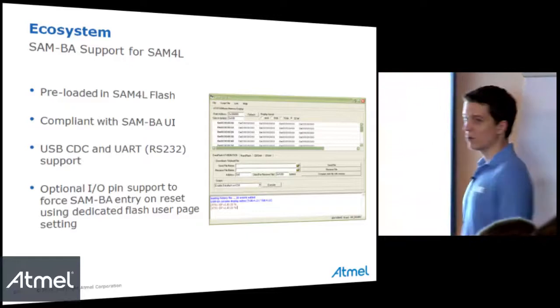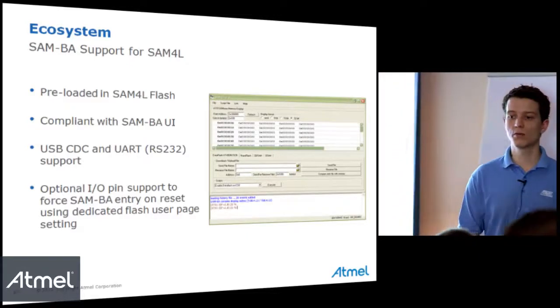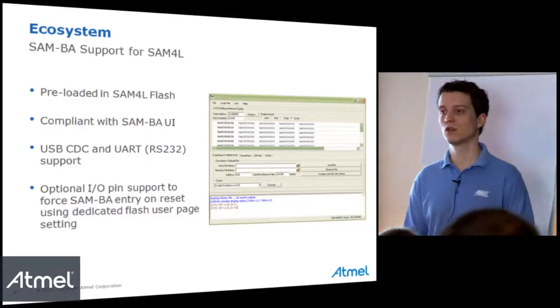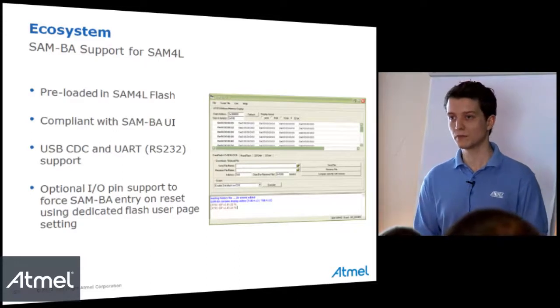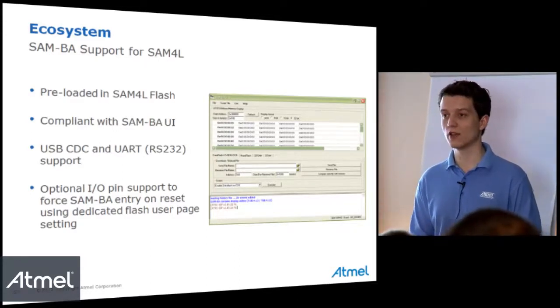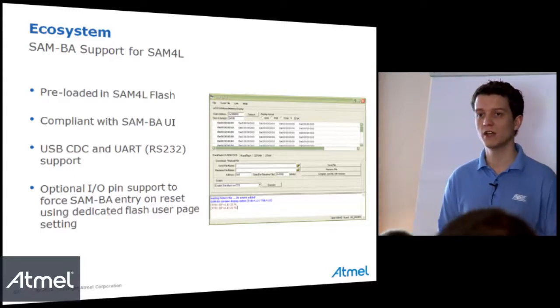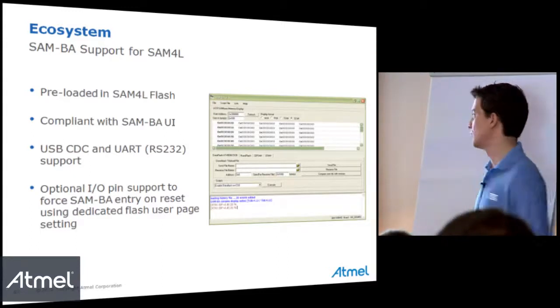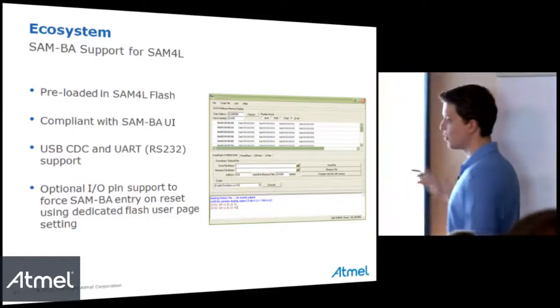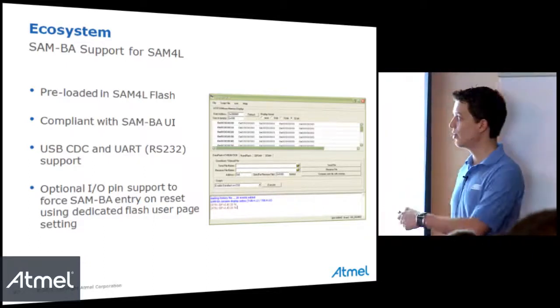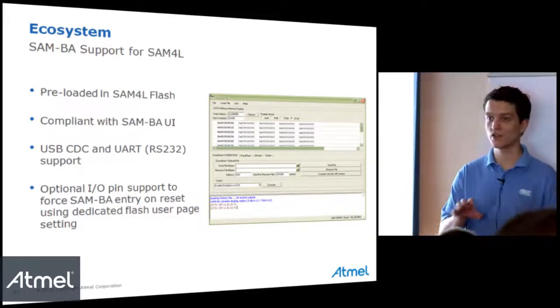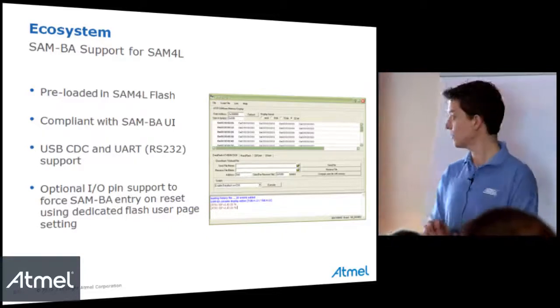Concerning SAM-BA support, SAM-BA on our previous SAM products was stored in ROM, but we don't have ROM on SAM4L, so we changed a bit the way to use the SAM-BA code. It's now preloaded in SAM4L Flash, so it's a Flash bootloader code.